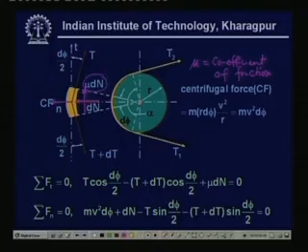There is a centrifugal force that will be acting onto this belt segment and which has been given as a value Cf, and this value of Cf is computed over here. Here you can see the centrifugal force Cf is nothing but m r d phi. What is this r d phi? r d phi is the belt length, and this m is actually what? The mass of the belt of unit cross section for a unit length.